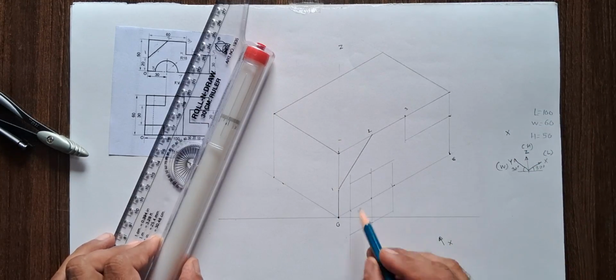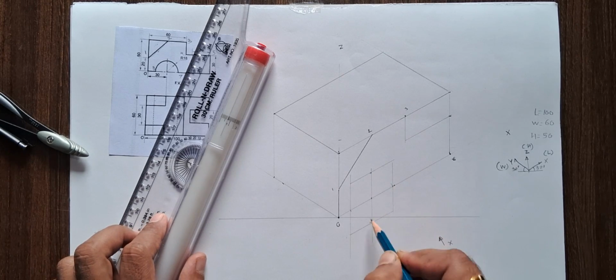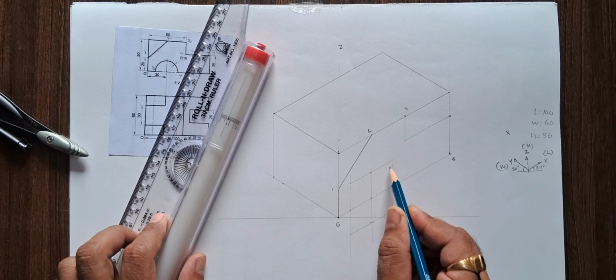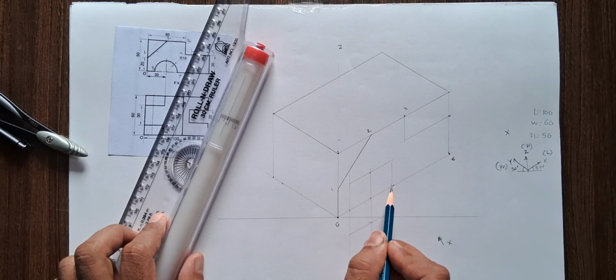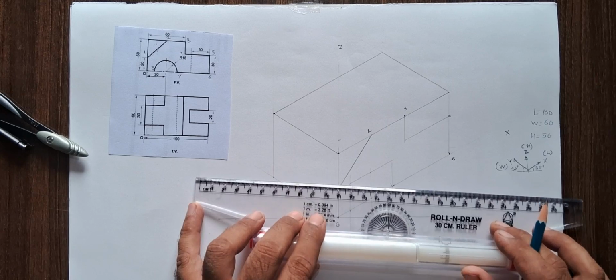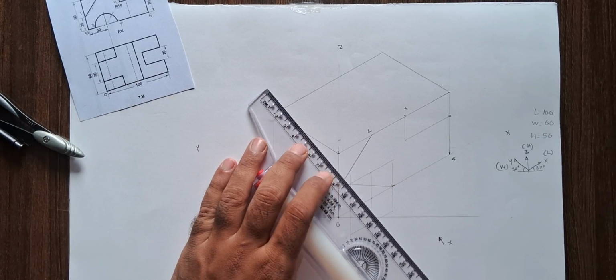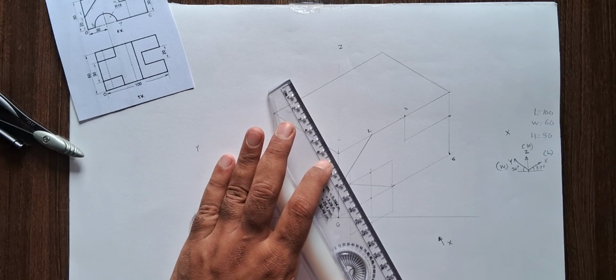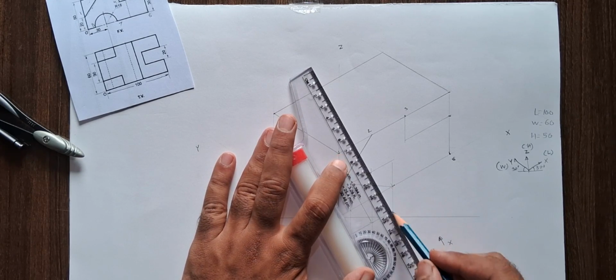You can see we have made a rhombus here. Before that, these are the center midpoints of this rhombus. Now these two are the obtuse angles. Now join the obtuse angle and the opposite side midpoint. There are two obtuse angles, and in front of each obtuse angle there are two lines. This method is called the 4 center method.